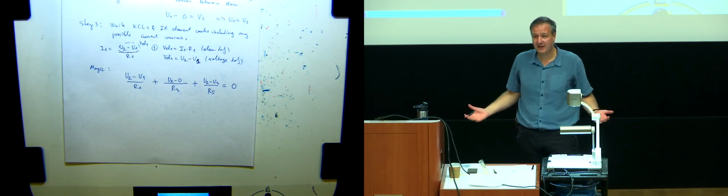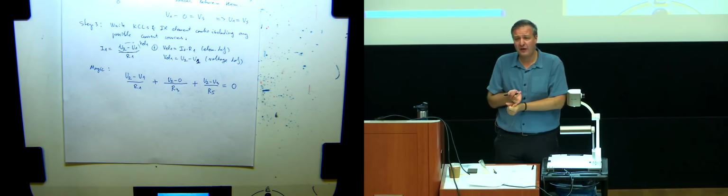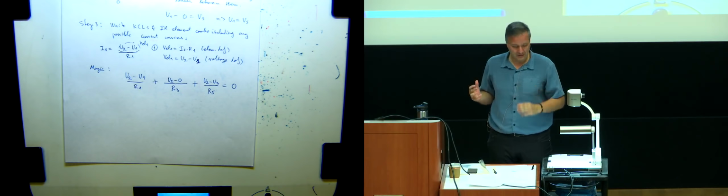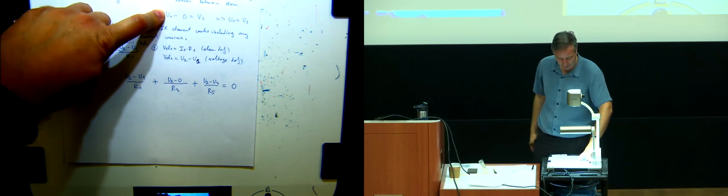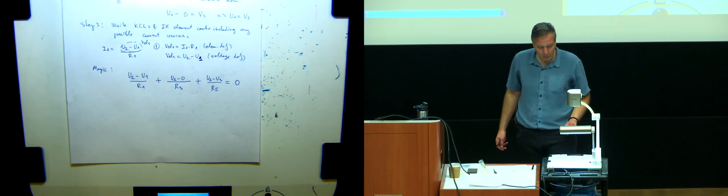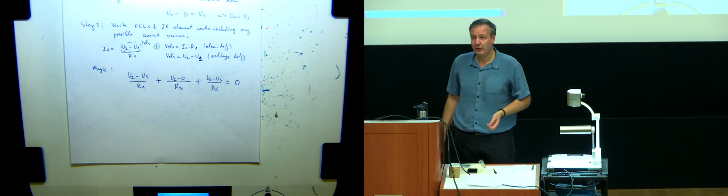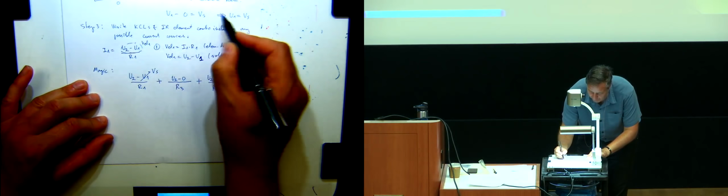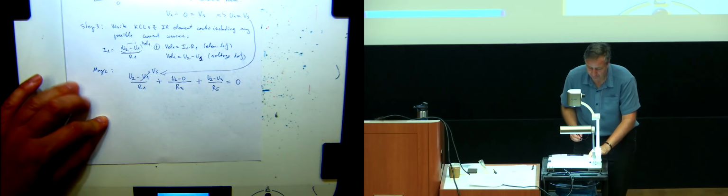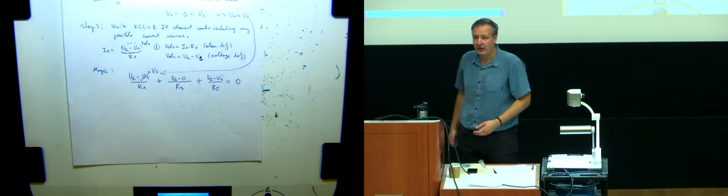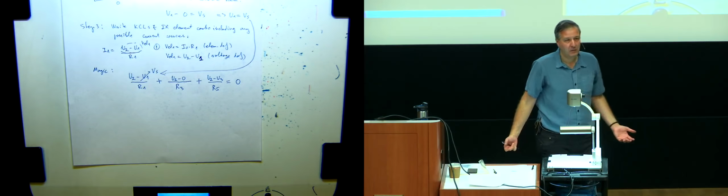See how simple this is? I don't have currents as variables. I have a minimum number of unknowns, which are just my unknown potentials. I already cleared U1, so that's out of the picture. I can replace it here with Vs, right? So I only have two unknowns. That's U2 and U3. So this one we already know is Vs from here. Okay, so I have two unknowns, U2 and U3. What else do I need to do?